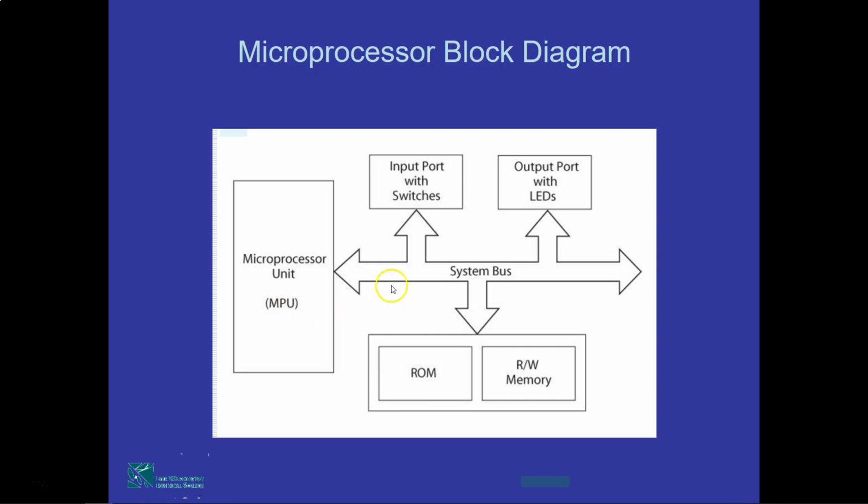But there are some limitations with the microprocessor. It requires an external memory chip, which you can already see here. This memory chip is needed to hold the programs and data because the early microprocessors did not have on-chip memory. It also needs glue logic such as address decoders and buffer chips to interface with the memory chip.